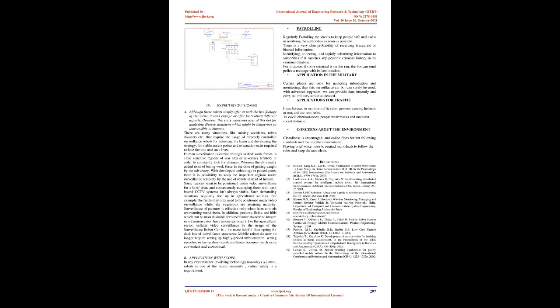You should open up your router settings. There you will find some settings, including something along the lines of forwarding or port forwarding. The important thing to note here is the port range and the device or IP address. In port range you should type 80 to 81. For device you should select your ESP32-CAM device. In some routers you should put the IP address of your ESP32-CAM instead of a device name. The live video captured by the camera will be sent to the Android application by which we will decide the movement of our vehicle.